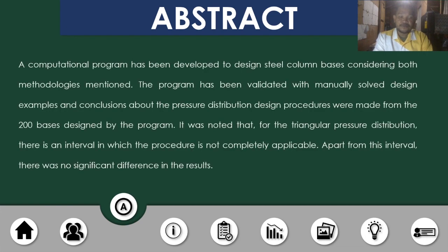A computational program has been developed to design steel column bases considering both methodologies mentioned. The program has been validated with manually solved design examples, and conclusions about the pressure distribution design procedures were made from the 200 bases designed by the program. It was noted that for the triangular pressure distribution, there is an interval in which the procedure is not completely applicable. Apart from this interval, there was no significant difference in the results.